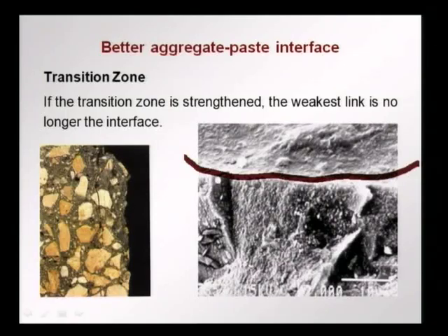So, when high strength concrete breaks, you will see that the aggregates are also broken and you have a plain smooth crack face. This makes the concrete more brittle, but it also makes it very strong. This is something that we have to keep in mind. The aggregates, when they break, increase the brittleness of the concrete, and when the crack goes around the aggregates without the aggregates breaking, then the concrete is less brittle.